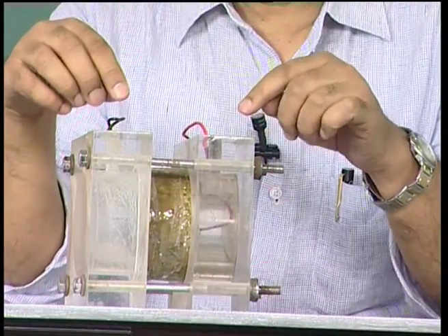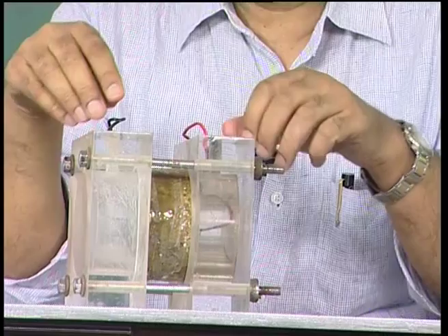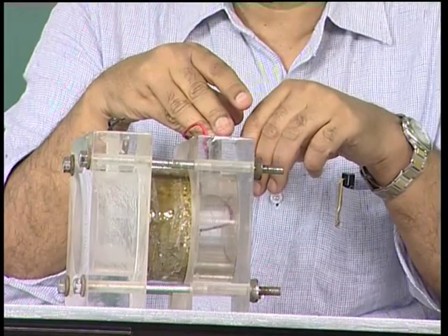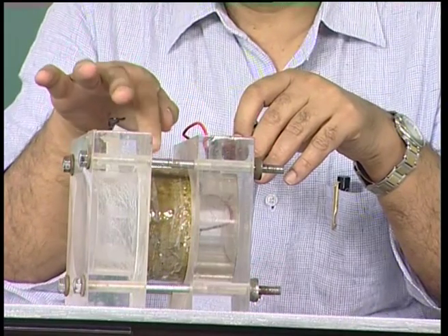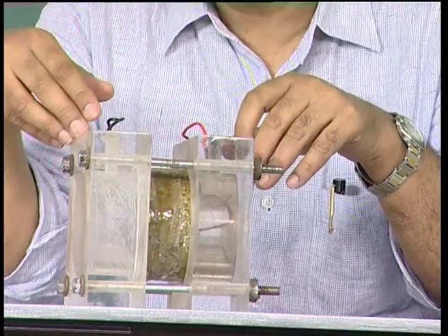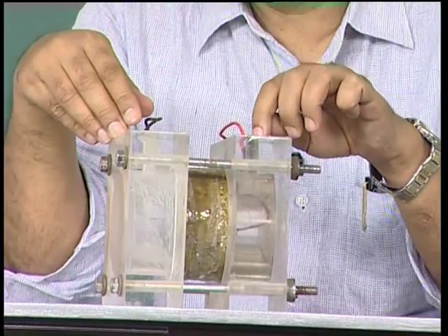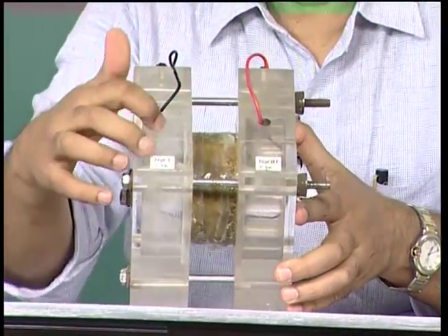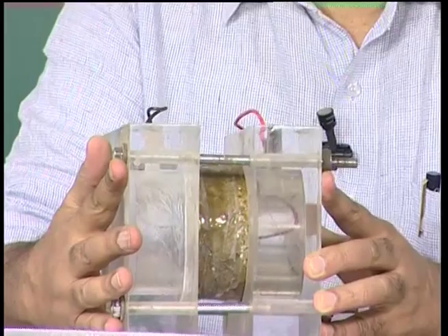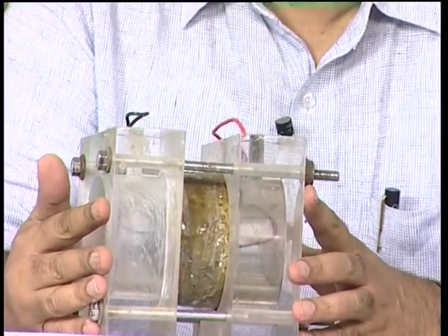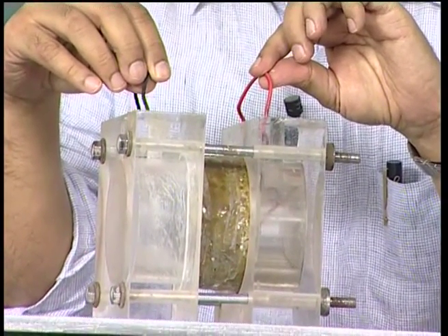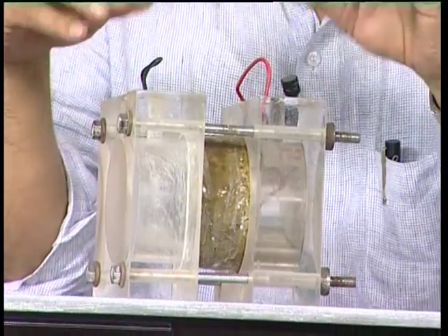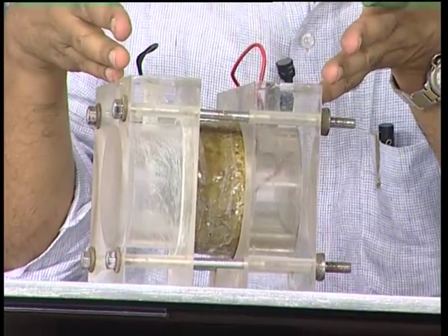If we want to regularly sample whether the chlorides are coming on to the other side or not, whether they are traversing the concrete thickness or not, or what is the rate at which they are doing that, we can always have probes through these holes that are there on the reservoirs. As far as T277 kind of tests are concerned, we can use these wires which are connected to the meshes that we saw to impress a certain amount of current across the two faces of concrete.